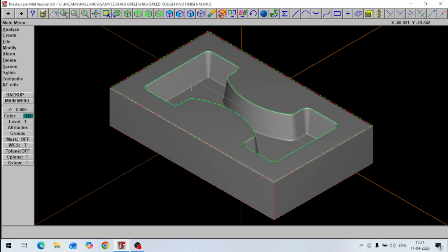And what we have to do in the milling is this cavity, roughing and finishing of the cavity. First we have to do roughing and then finishing. And this is the profile given here. This is a 2D profile, and this is a solid like this. So how to do it? We have to create two types of tool paths. One is the roughing tool path, 3D roughing, and another is the contouring tool path, 3D contouring. So how to do that?